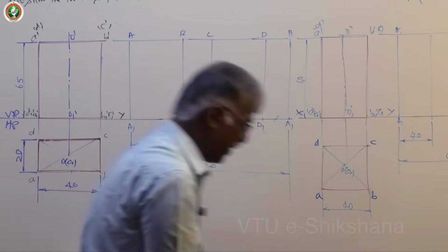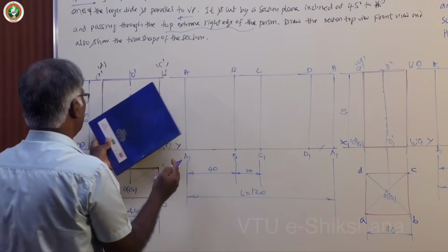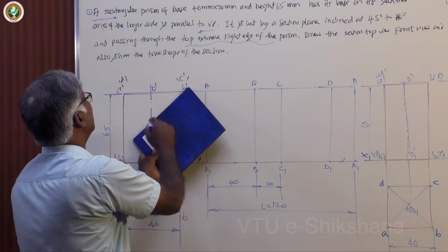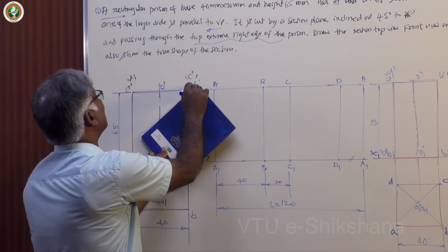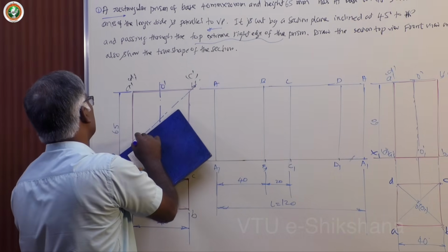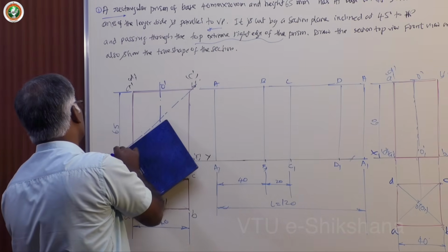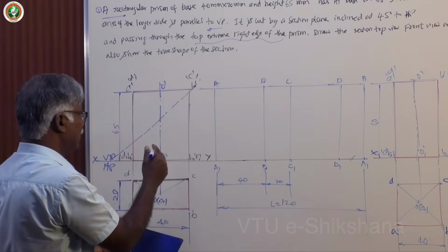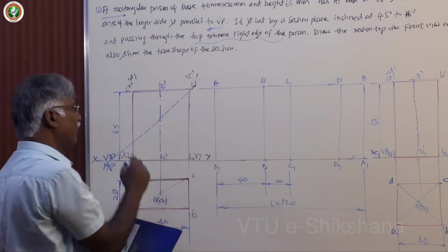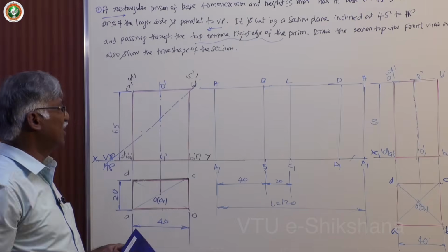How to draw the section plane? This is very simple and easy. Now, there is a convention. Assume that I am taking 45 degrees from the right, this one: full line, hyphen, full line, hyphen. Almost like the axis, but for the axis we can keep a dot or a little small hyphen. Here it is full line, hyphen, full line. There is a convention here.